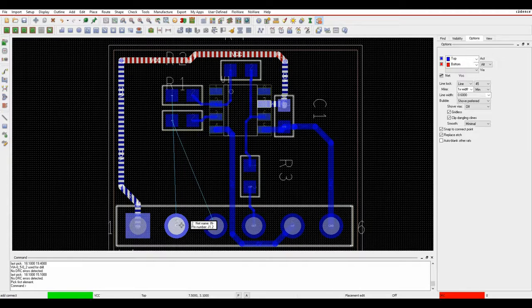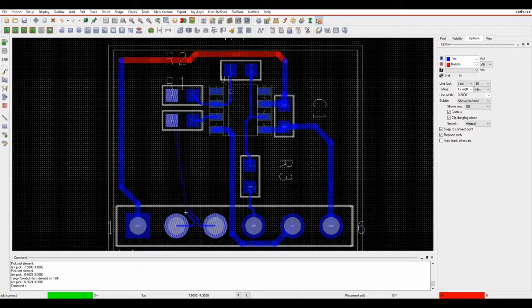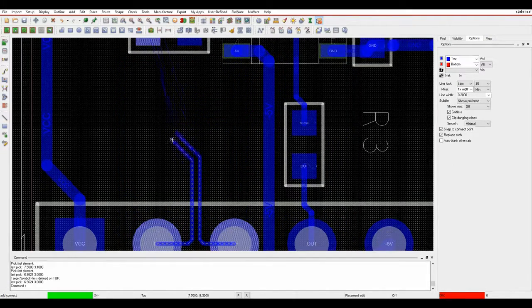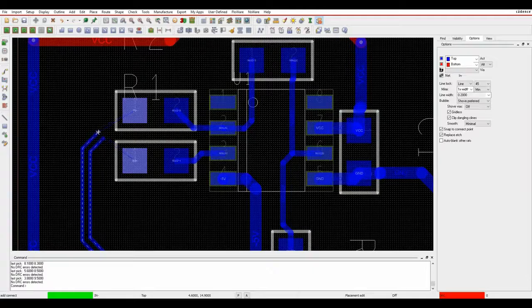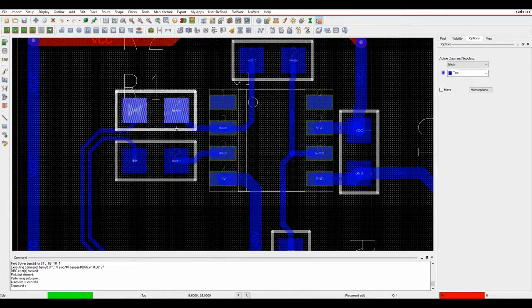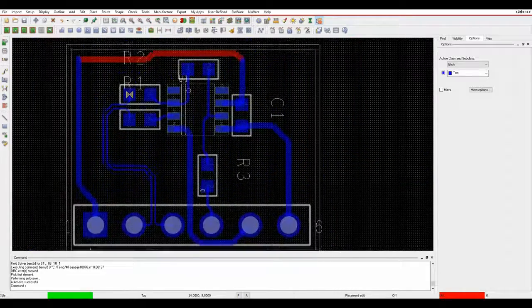And then finally, from a routing point of view, when I click on one of these pins, obviously this is the differential pair that we defined. Both traces jump together, so you can see I effectively get, based on the rules that we specified, and I can just route around. So let's come in something like this, and then I can go and finish the traces. And that routes the differential pair.